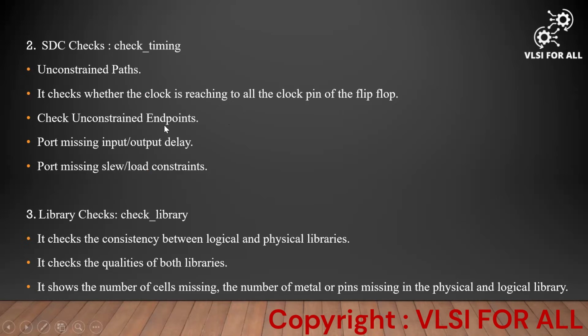And the next one is checking unconstrained endpoints. Any endpoints that are unconstrained need delay constraints on those particular endpoints. If any ports are missing an input external delay or an output external delay, it will be triggered as a timing issue. And the next one is if any port is missing slew or load constraints, that also we have to report in the check_timing category, meaning it is not driving any load properly or the result is not as expected. Likewise, we have to report this under check_timing.